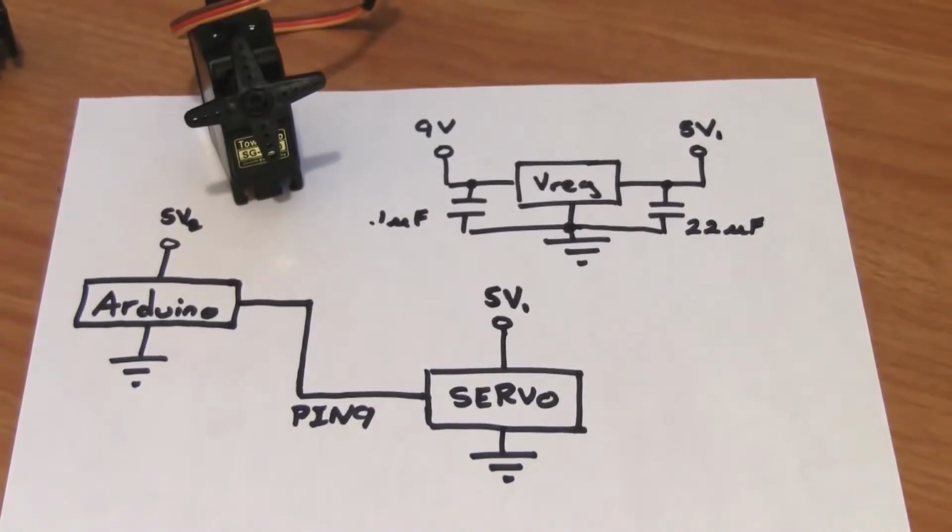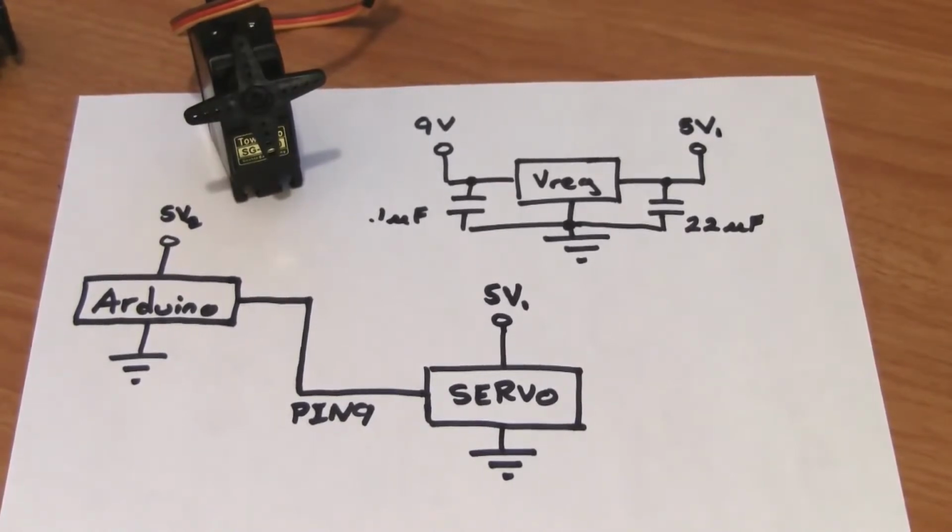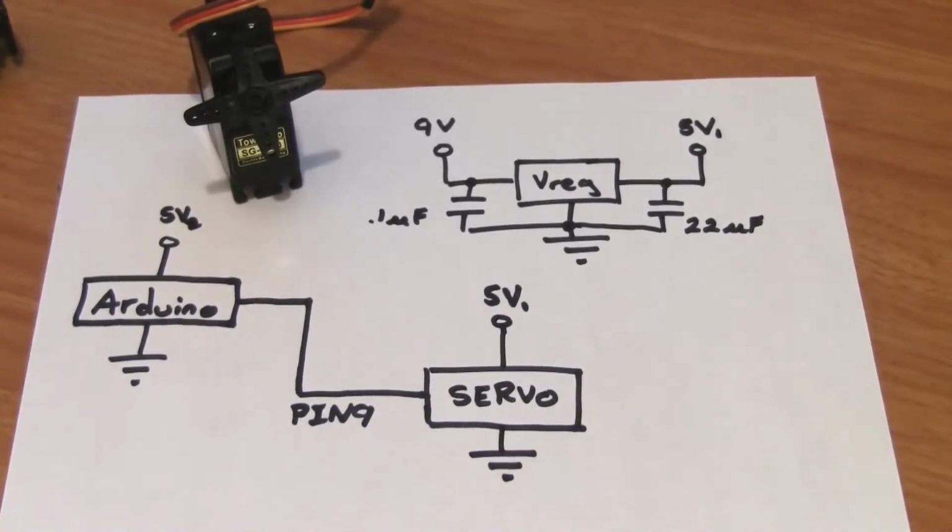Now we're going to control a hobbyist servo motor, like this one. Servo motors are much different from DC motors. Instead of just giving them a constant voltage and watching them rotate forever, servo motors respond to a PWM signal. Depending on the value of the PWM signal, the servo will rotate to a particular location. In the case of this servo and many hobbyist servos, it is limited to 0 to 180 degrees. Based on the value you send it, it will rotate to an exact predetermined position. This is really useful for a lot of projects.